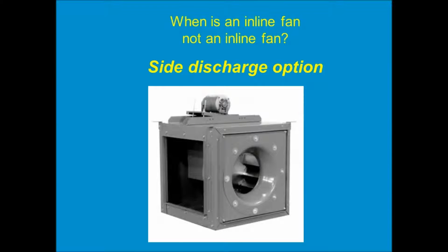Here's a little pop quiz for you. When is an inline fan not an inline fan? Well, it's when we use the side discharge option. Because this square inline fan is really just a pressurized plenum, that little centrifugal impeller is like a little plug fan. It's just drawing air in and pressurizing the box.